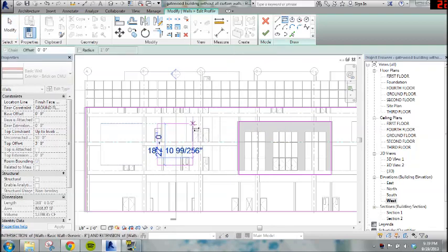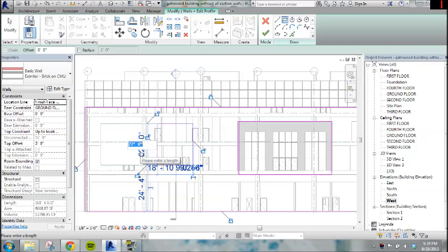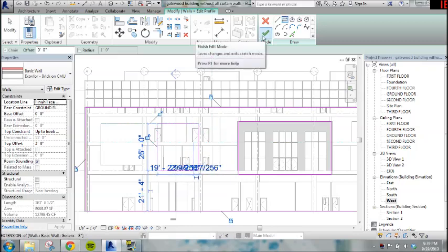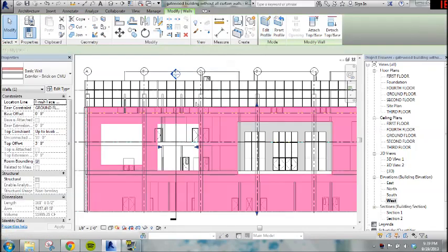and draw floor. This is going to be 25 feet tall and 22 feet wide. Okay. And just like when we were making floors, you need to push the green check mark to complete this tool. Now, we have one more step to make this opening a curtain wall.